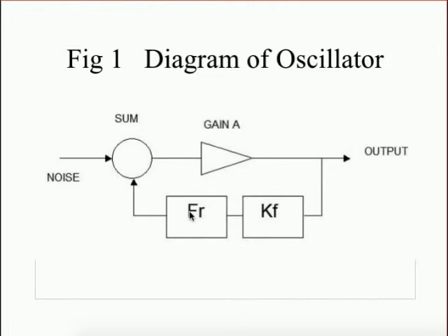I should also mention that the variable Pin we've used, the input power at the amplifier, I've sort of loosely called it Pin, the input power to the amplifier. Now strictly speaking we should call this the available power. When an amplifier is being noise matched at low levels in receiver type systems, it's not actually the input power that matters, it's the available power.